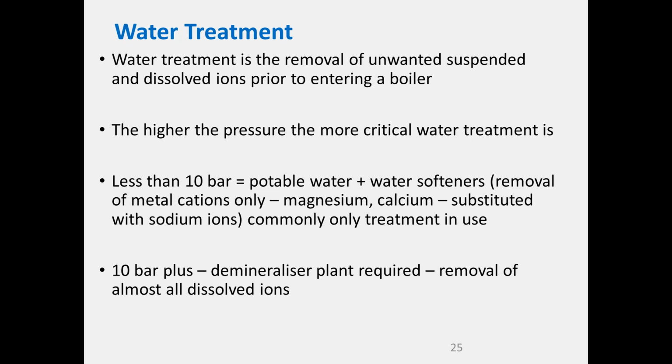That is commonly the only treatment in use. And that kind of works and kind of doesn't. If you're operating at more than kind of 10 bar plus, really, my recommendation is you need to consider what we call a demineralizer. And this removes basically all of the dissolved ions.